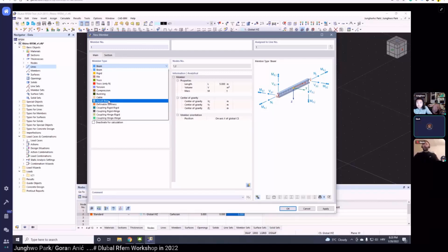for some structures. For example, if you have a connection of two walls, or some specific place inside some part of your construction where you need to check your results, then you can enter a line and put the result beam. This beam will not be a real member; it will be used just to show the results in this section or at this position.